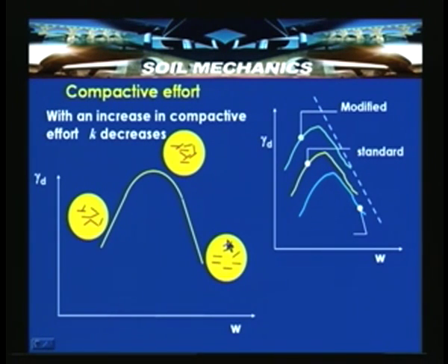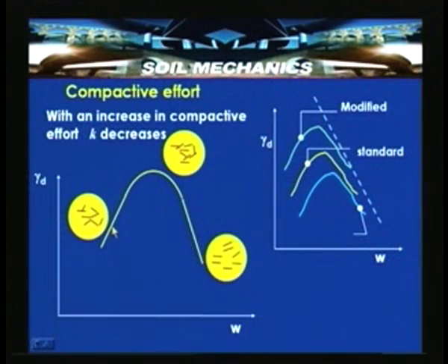By using the same logic we discussed, the permeability value on the dry side of optimum will be very high compared to the wet side, for soil with the same void ratio or same dry unit weight. The soil with a flocculent structure can have higher permeability compared to the soil with a dispersed structure.